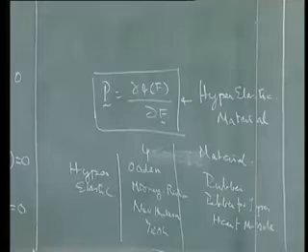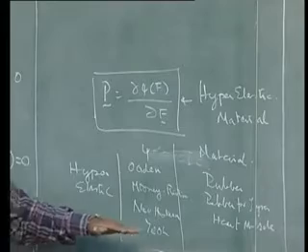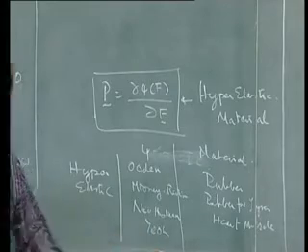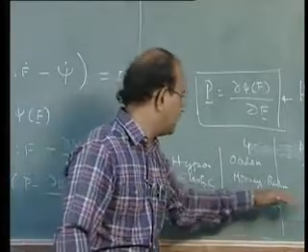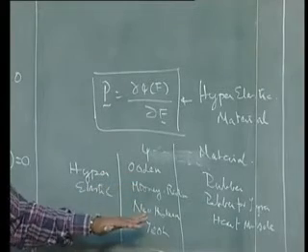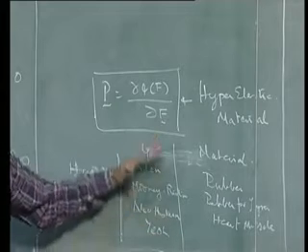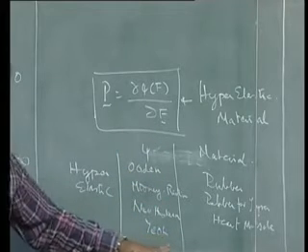Some of them, for example, rubber for tires can be represented exceedingly well as a Yeoh material, not so very accurately as Mooney-Rivlin material or Ogden material, and so on. In fact, when you come to heart muscle, the type of strain energy function is totally going to be different.